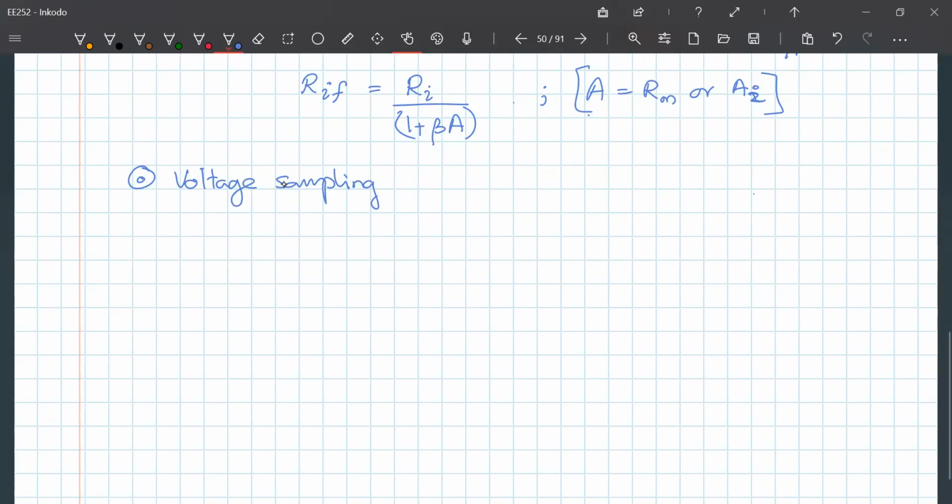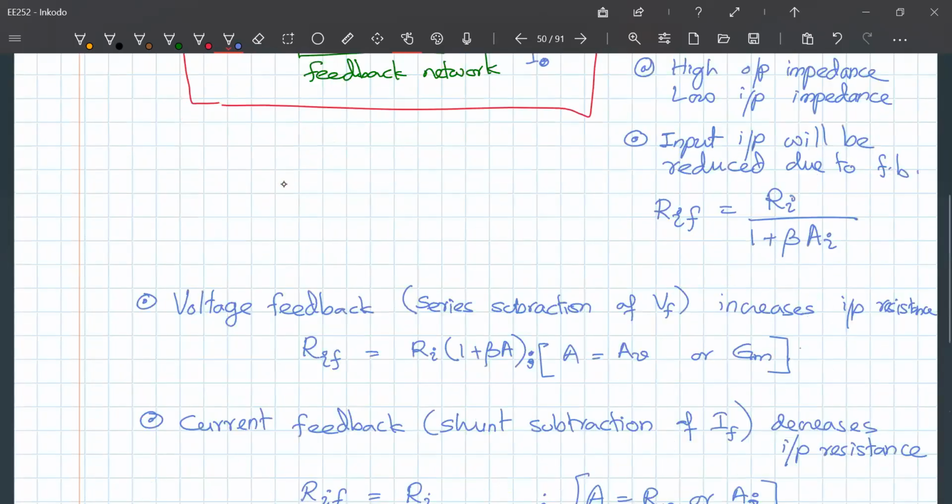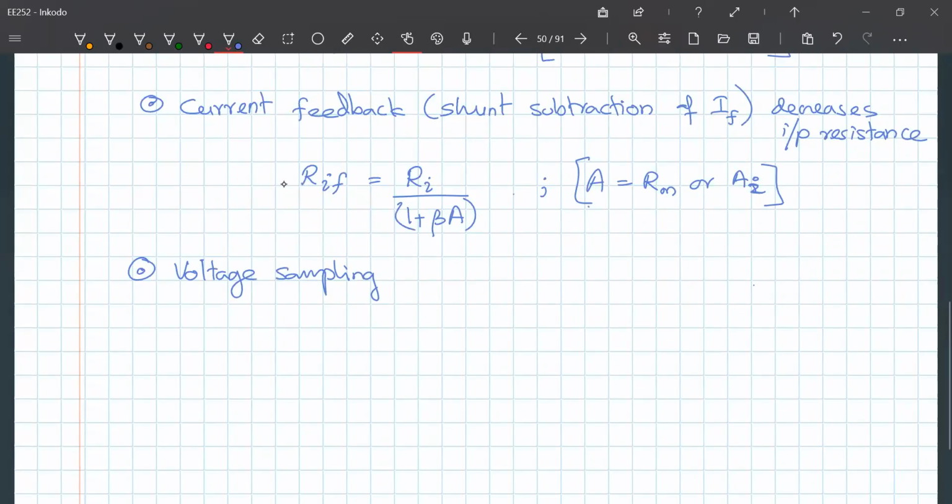In the cases that we considered earlier, they had infinite impedance, right? The input impedance of these were either 0 or infinity. In the case of voltage sampling, it was infinity. Current sampling, it was 0, but that may not be the case all the time. Sometimes they have finite impedances. If that is the case, if you put a finite resistance in parallel with the existing output impedance, the output impedance with both these in parallel will be smaller than whatever is the smallest impedance.